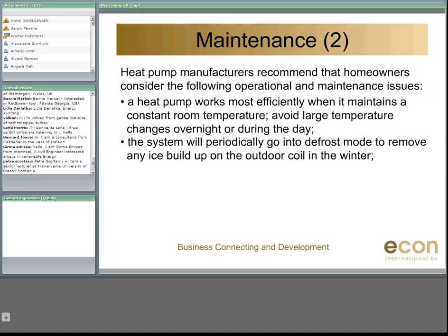The system can go to a defrost mode if you have the unit outside your house. Please make sure that it is not covered with ice, and if you have some ice on it, it must be removed, and then it will go to a defrost mode. But during defrost you cannot heat your system or your house, so please be aware of that when you have an air source system.